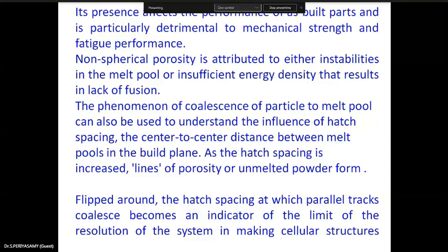If I have any variation in the cooling rate, or if it is not cooled properly, gas will be locked within. Then you have formation of the consolidated layer of this material. Then the melt pool. Here, what happened? You have a rapid solidification effect. Some places may rapidly solidify, and other quality issues arise.